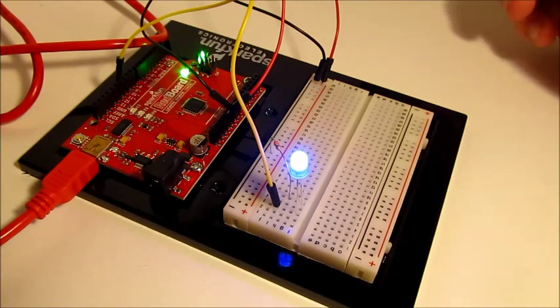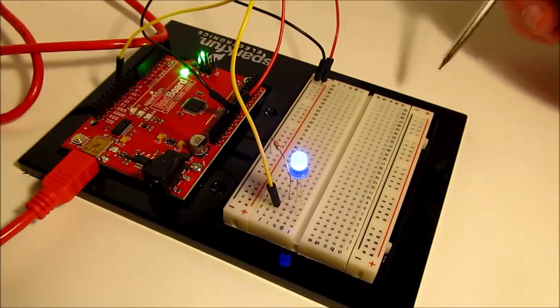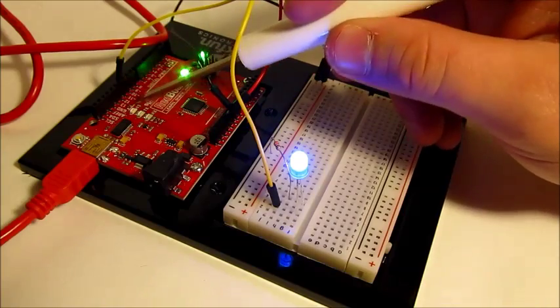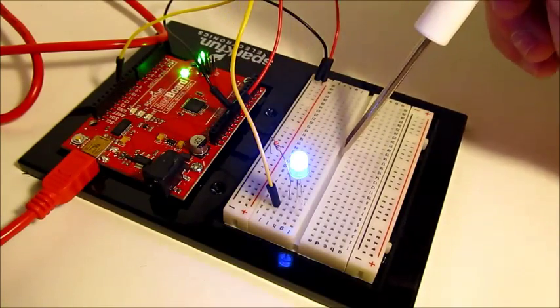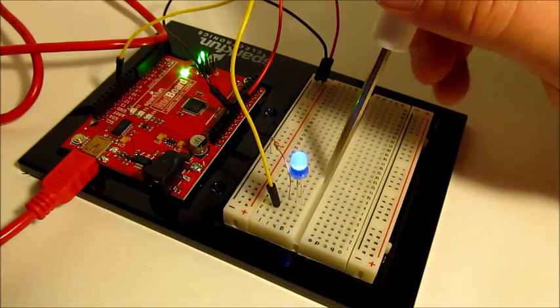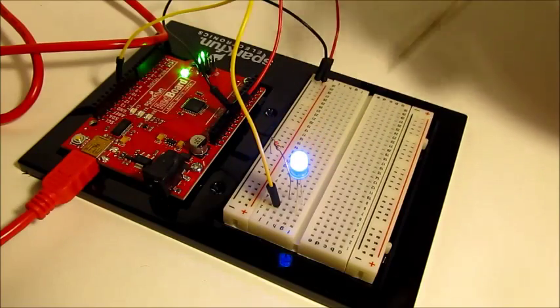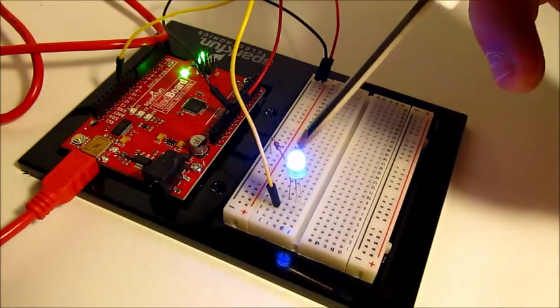This is objective 1, where we are using pulse width modulation to control the intensity of an LED's brightness. So what we're doing here is we are using pin 11, which is a PWM, or pulse width modulation, digital output pin. What this is doing is sending the power in a waveform, up and up and up and down. And this comes out to be various voltage.